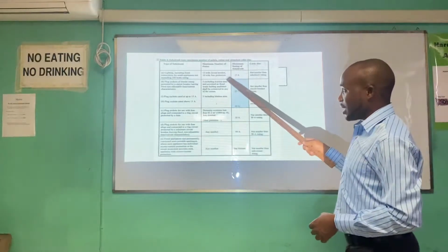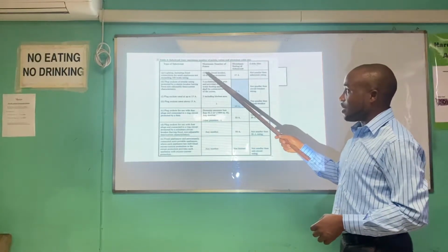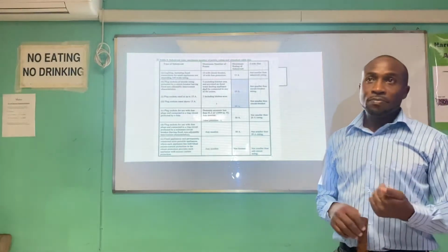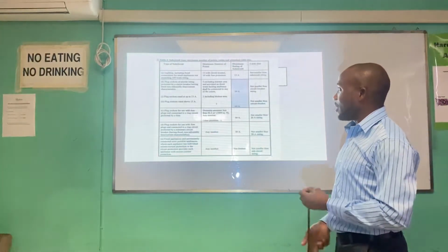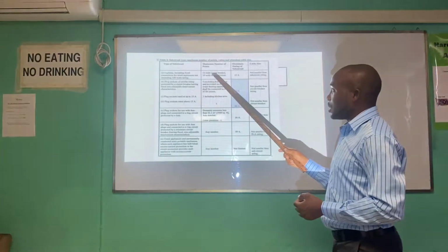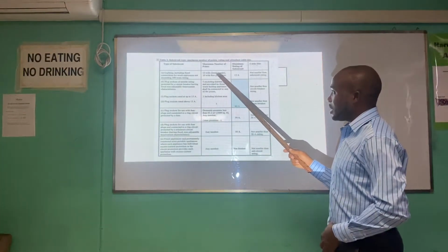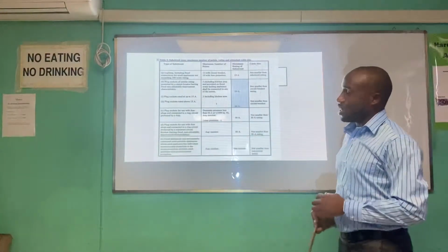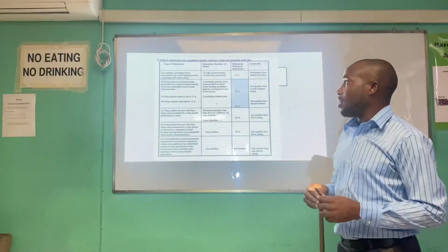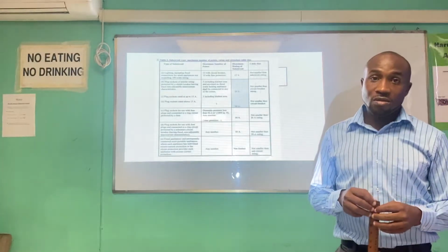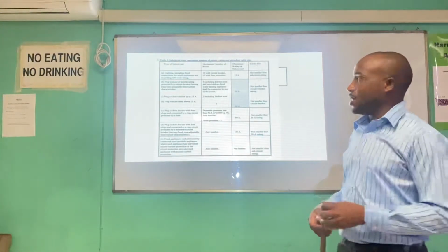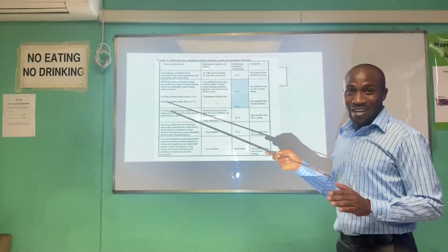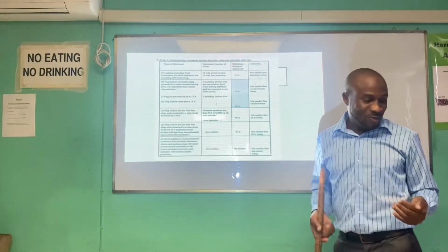So you have different protection. You can have fuse protection or you can have breaker protection. But usually for our application locally, what we find is used in our local residential and even commercial application is that the breaker is a more popular means of protection. And I might reiterate the fact that the breaker is used to protect the wire. Fine? Breaker is used to protect the wire.